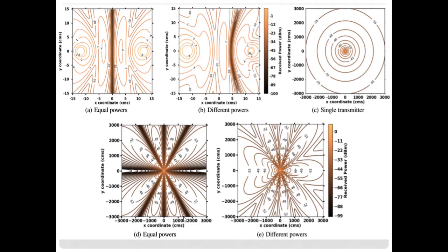In case of two transmit antennas, the signals from the two antennas get added constructively or destructively at the receiver at distances much larger than the spacing between the transmit antennas. The signals from both antennas undergo almost equal attenuation. With equal received power from both antennas, perfectly destructive combining of the two signals causes the received signal to be zero power.